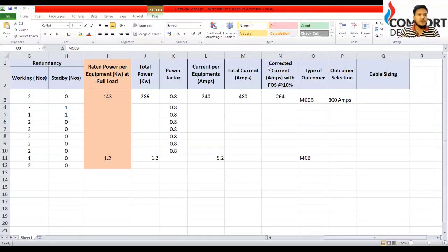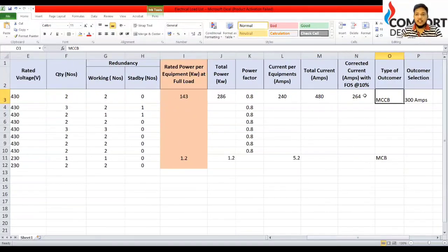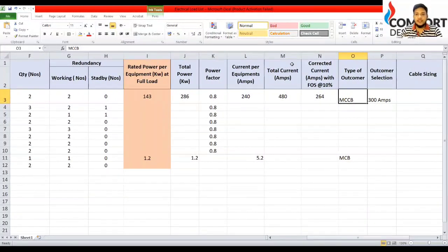Okay, there is one query from Mr. Sari: a 20 HP VRF outdoor unit is 16 kilowatt, how can the transformer be selected for such a system? So transformer selection will be based upon your HVAC load. Then we will have another load of firefighting, then plumbing, and then the other electrical load. We will add all these loads, and accordingly the selection of the transformer will be done.